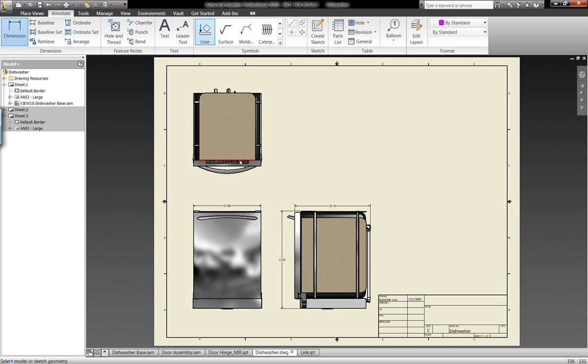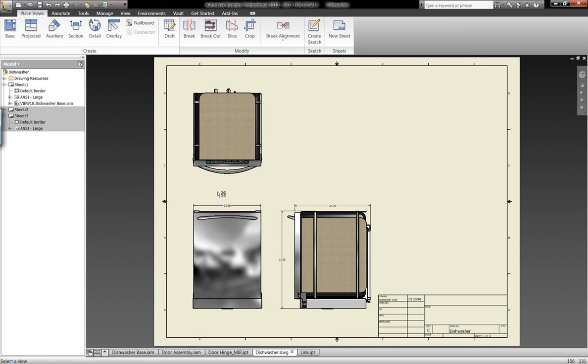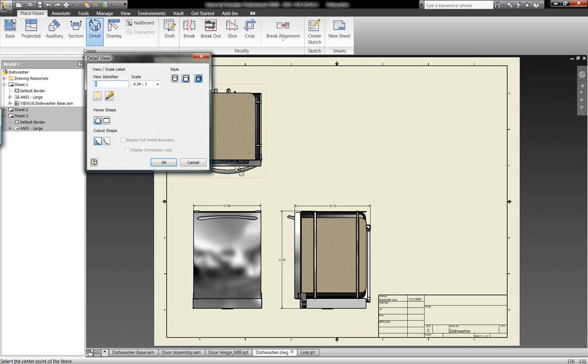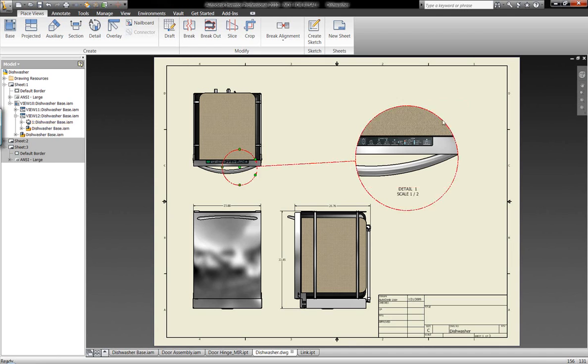So there are some specific dimensions that we want within this drawing. We'll go ahead and place each one of those dimensions. We also might want to place some detailed view perspectives or orientations within this drawing space as well. We can control the actual identifier or the naming convention of each one of these views. We can control the scale independently of this detailed view that we're working with here, and we can also independently control the shading as well.